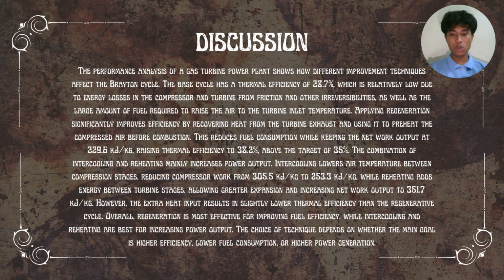Overall, these results show that each improvement technique has a different impact on performance. Regeneration is more effective for improving thermal efficiency and reducing fuel consumption, while intercooling and reheating are more suitable when higher power output is required.